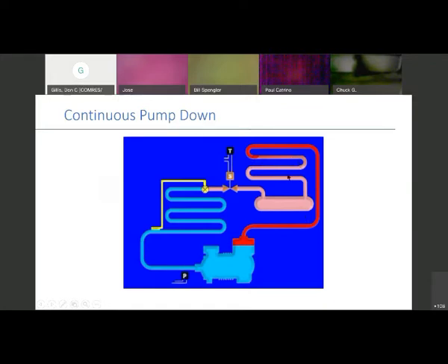And this is our condenser, obviously, and then our storage vessel, or our receiver, okay? And it comes on through all the way through the cycle. The thermostat then satisfies, okay? The solenoid shuts down, normally closed, okay? But the compressor keeps running, okay? And it keeps pumping down.